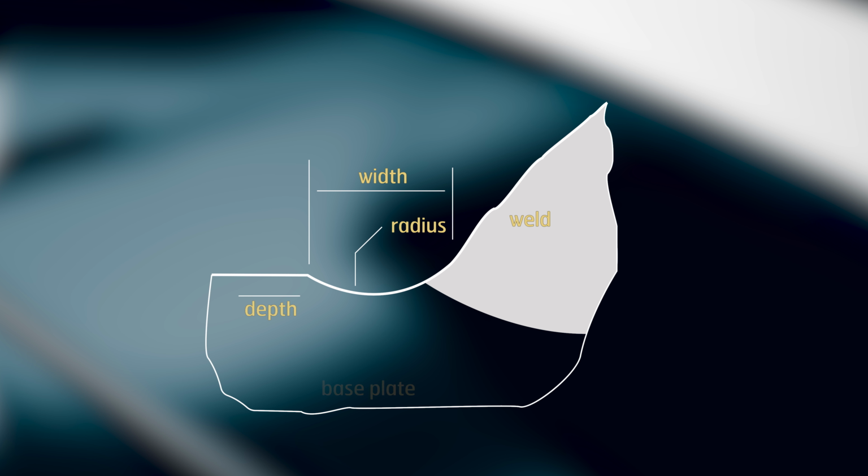The result of the HFMI treatment is an improved geometry of the weld toe, and it will also introduce compressive residual stresses in the weld toe that will prevent a crack to appear. HFMI treatment is suitable for most common weld methods and all steel grades, and can be done manually or by robot. It is not very complex. So, let's look at some results.